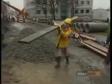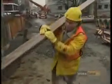Shoring uprights must extend above the top of the excavation by at least 1 foot, and must be as close to the bottom of the trench as is possible, but in no case more than 2 feet from the bottom.